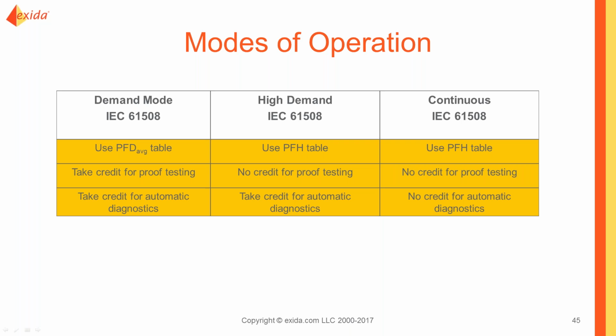That LOPA diagram was basically, you do the LOPA to determine how much risk reduction you need for the safety-related control function. The order in the LOPA doesn't necessarily mean the order that the protective function would actuate. You might have a control function first, then a safety-related control function, and then an alarm. That might be the actual order in which you set up the machine to work, or the precedence of priority you give things. But when we're doing that LOPA calculation, we're trying to calculate how effective everything else is to determine how good our safety-related control function needs to be.